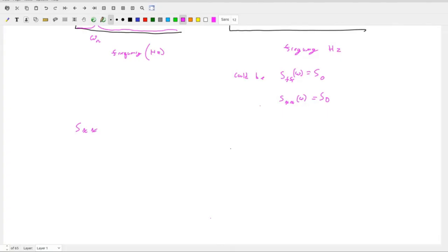So for a 1 degree of freedom system considered here, we can express the arbitrary input as a series of impulses, as discussed before. This knowledge, along with the response function, can relate the spectrum of the input, SFF, to the output, SXX, and allows us to build this into an equation. Again, the idea here is that we can model this spectrum as a series of inputs. Does anyone disagree with that statement? So we can do anything with a series of inputs. We showed that with the hammer example.